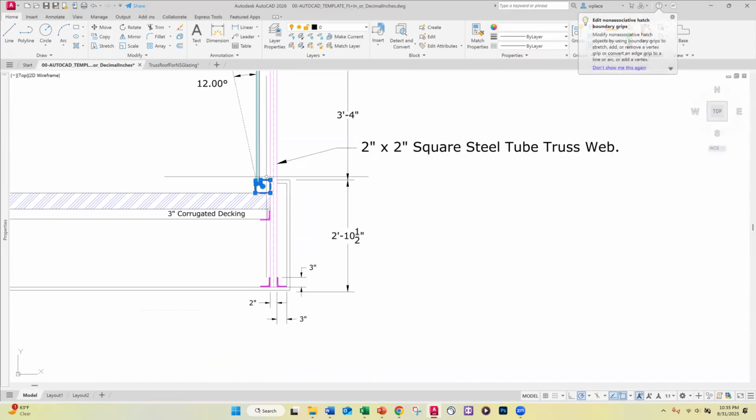So this is a kind of a mullion that grabs hold of the glass. It's also the curb at the upper part. So we'll put some kind of single ply membrane that glues to that face and comes out over the top surface of this insulation.